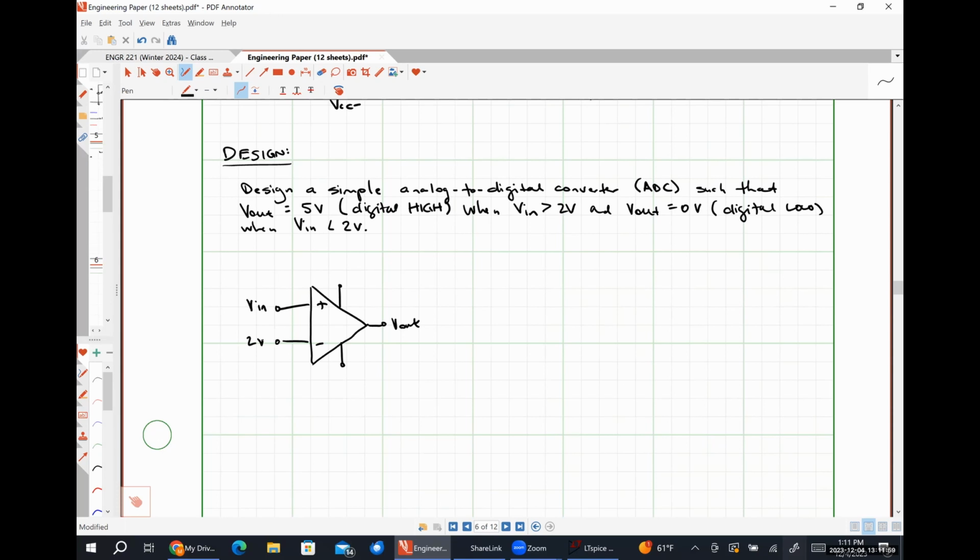All right. So what do my supply voltages need to be? 5 and 0. Which one's which? I mean, it's kind of obvious, but 5 volts has to be VCC plus. Put ground as our reference. Congratulations, you guys have just designed your first op-amp circuit. Just as a heads up, this is exactly how the analog to digital converter in your Arduinos works.